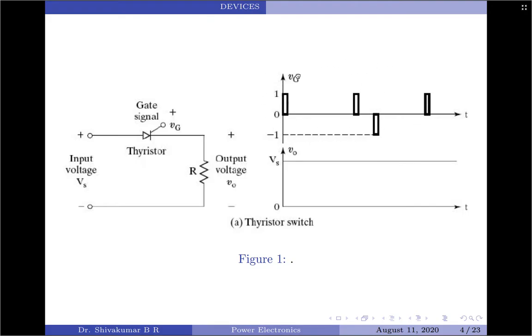So here we have given the gate voltage at exactly time t equals 0, and that is the reason why you are getting an output voltage starting from t equals 0 itself. If instead I had shifted this pulse a little to the right, then you would only get the output voltage from the instant at which the gate voltage is applied.